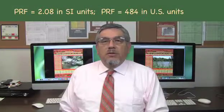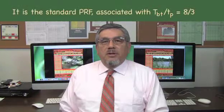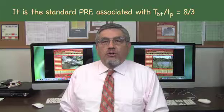The number 2.08 in SI units and its equivalent 484 in U.S. customary units is known as the peak rate factor of the NRCS unit hydrograph. It is the standard peak rate factor associated with triangular time base over time to peak equal to 8/3.